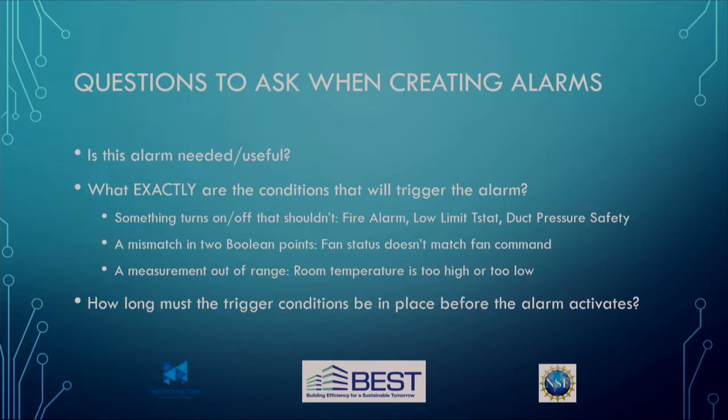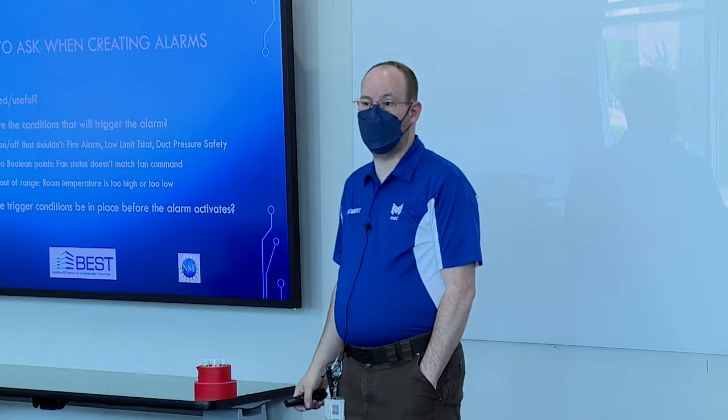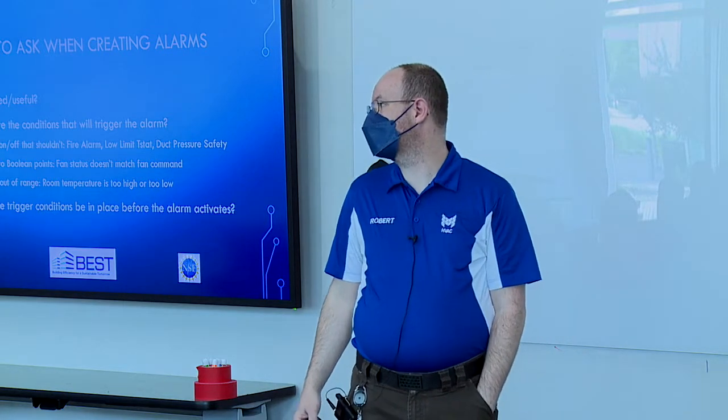First thing you should always ask about an alarm is, is this actually useful? Is it needed? This is maybe something that you, as an installer, can't answer without talking to somebody else, the building owner or building operator. Hey, is this something that's going to be useful to you, or is it going to be annoying? Okay, back to that conversation on nuisance alarms.